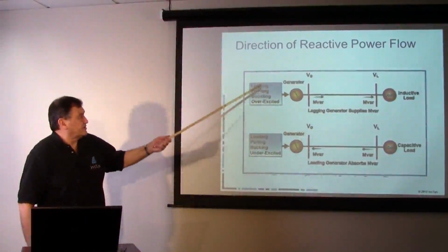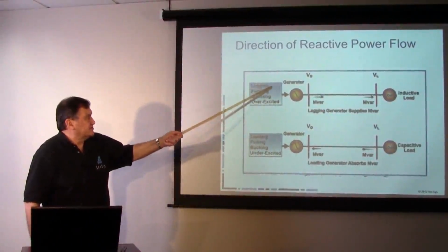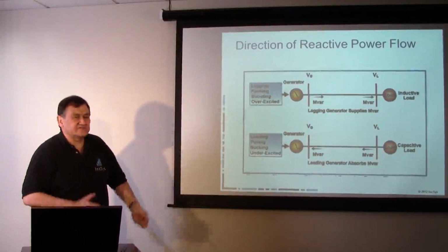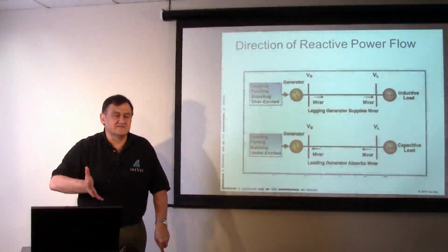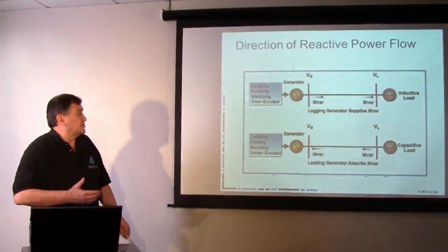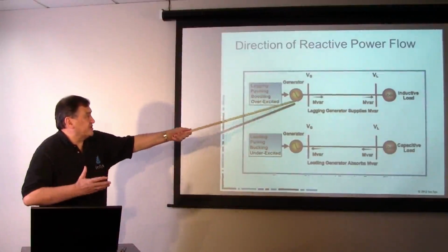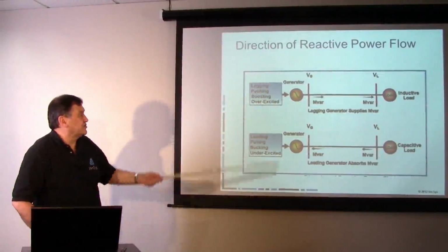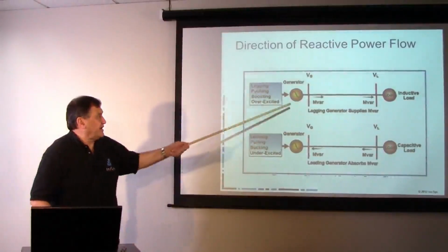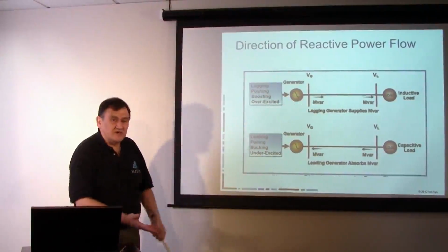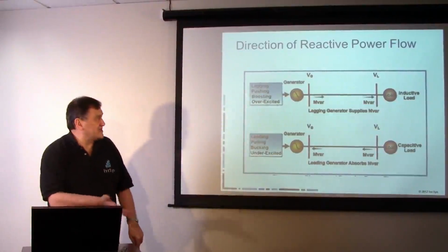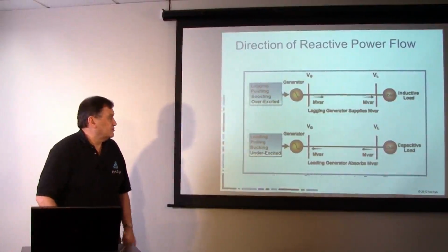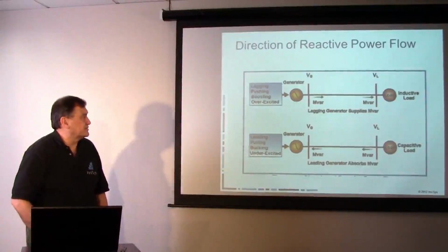And so it's important to realize the reference that the generator is lagging, but that is in terms of the fact that that generator is now serving a lagging inductive load. So we can say that generator is pushing megavars onto the system. We call it boosting because in this mode it is actually helping raise the voltages. So the idea is when we're raising voltage, we call that boosting. When we're lowering voltages, we call that bucking.